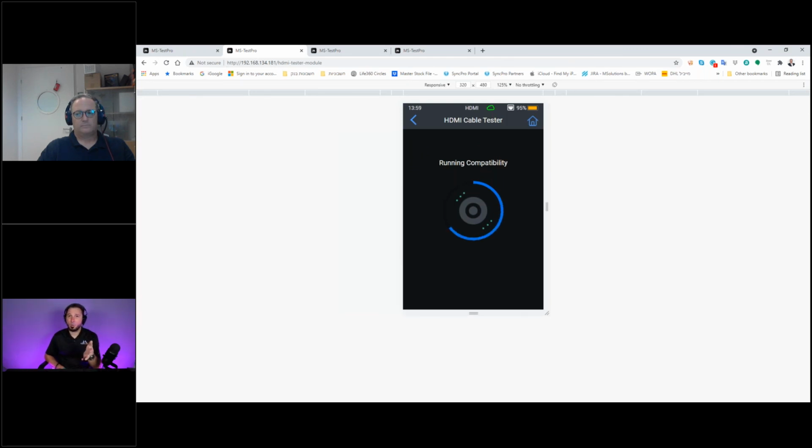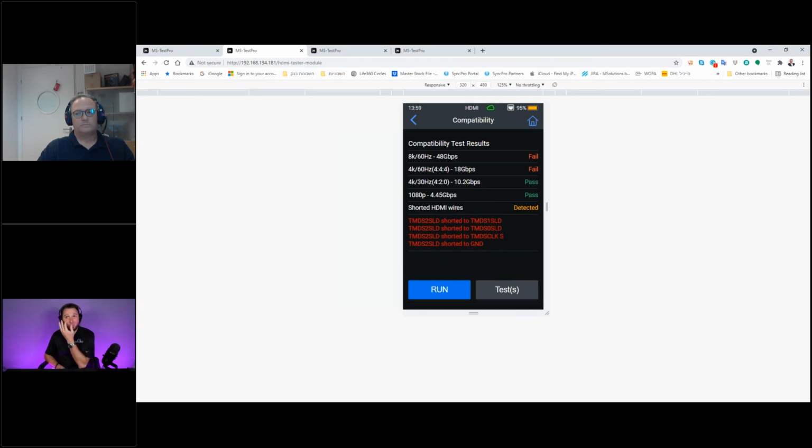But one thing I wanted to point out, guys, we're in a 48 gig world right now, and most people are transitioning to HDMI 2.1. The fact that you are testing 8K 60 is fantastic. That's a very important test that we're already dealing with now, and it's just going to get more important going into the future. That was Himani. Himani, I hope that answers your question. If not, go ahead and send a follow-up question into the question box.